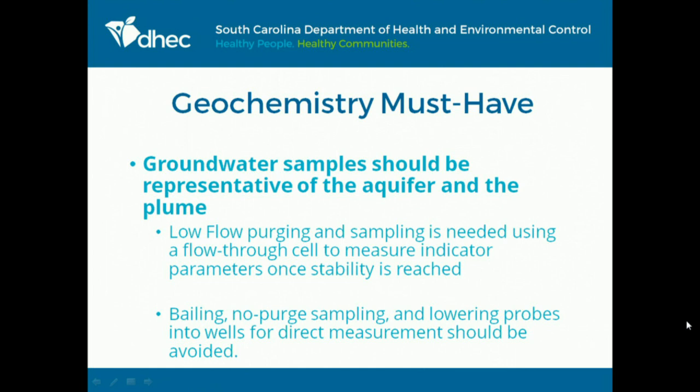That needs to be avoided. That's another thing that came out of the first decision tree when we sat down and started trying to use it, and we realized the data quality is so terrible we can't use it. We've got samples from bailers, they dried out the well, they had water trickling into the well, they grabbed a sample as soon as it was available. That means nothing. It's information, but it's not something that's usable. So that was a revision to this current decision tree.